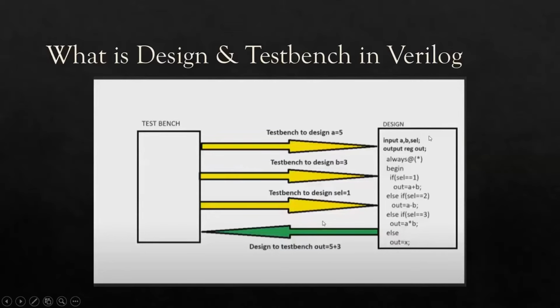Let's assume this is C code, and the inputs are driven by the user in C, like scanf. But here your user will be the test bench. Through the test bench, you drive the inputs to the design, and through the design you give the output to the test bench. This is the very simple logic I have written in the design part.